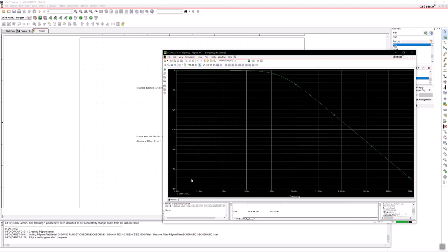Now, one thing we're always interested in is what's referred to as the cutoff frequency, which is the minus 3 dB point. And the reason we're interested in the minus 3 dB point is that is what was considered half power. That's where the output signal is at half power of the input signal. So that's why we're interested in the 3 dB point, is because we've cut the signal's power in half at that point. And then another minus 3 dB, you'd cut in half again. So in other words, it'd be 75% of what it would be originally. Okay, so then how do we do that?